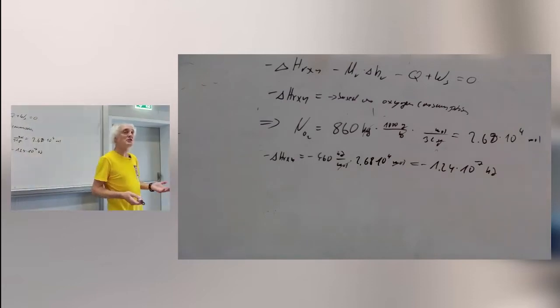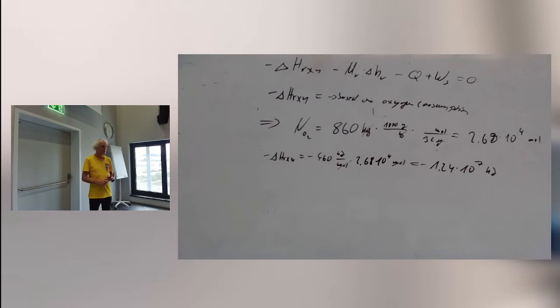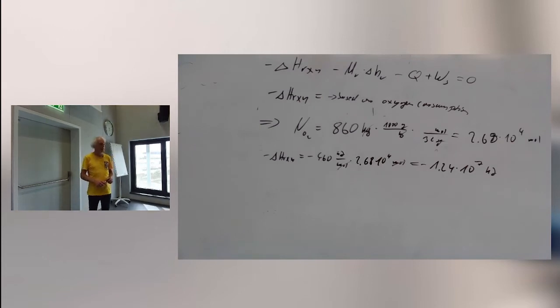The heat of vaporization, of course, you look up, you take the value from the steam table. I think the steam table was given in the Moodle exercise. I don't remember. So this value needs to be looked up or given. Make sure that you take the heat of vaporization at the correct temperature. Otherwise you would use specific heats to go up and down, but usually it's given at the correct temperature. Multiply that with the mass, don't forget that. And then you have your latent heat, which goes in your equation as minus, of course.